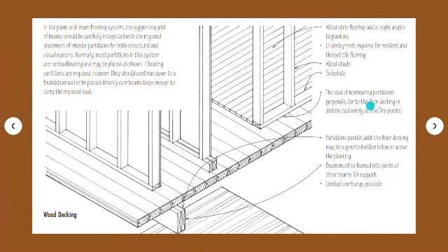Perpendicular to the floor decking, the load is distributed evenly across the planks. So there are the partitions parallel with the floor decking, which may be supported either below or above the planking, and this is the beam, which must be framed into posts or other beams for support, with limited overhangs possible. In the plank and beam framing system, the supporting grid of beams should be carefully integrated with the required placement of interior partitions for both structural and visual reasons.